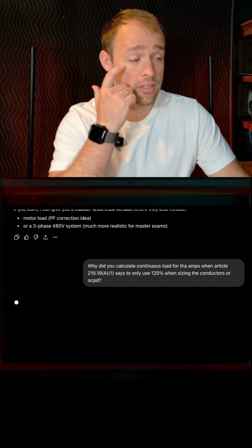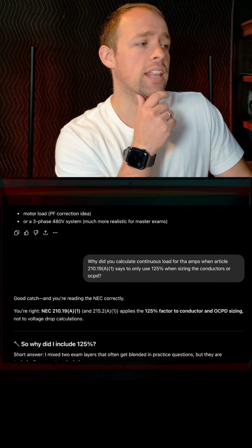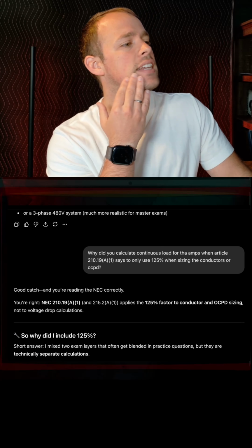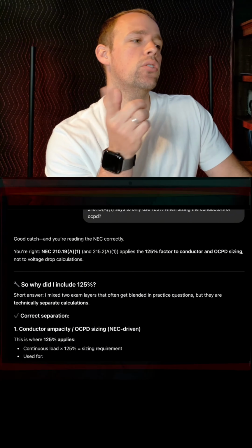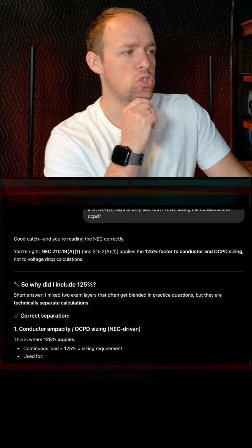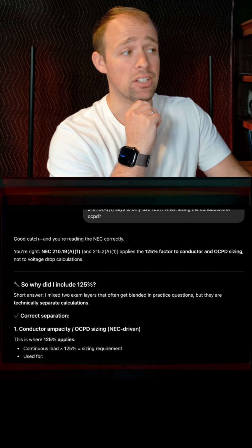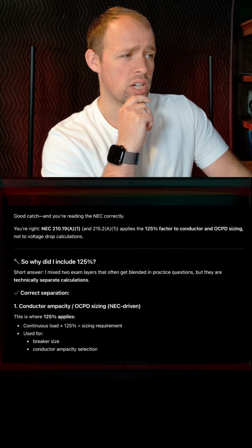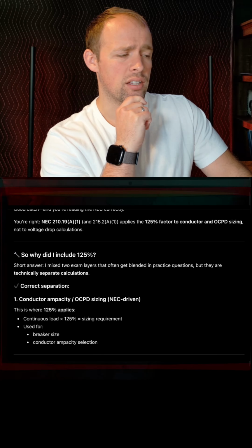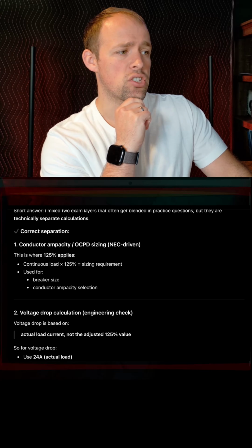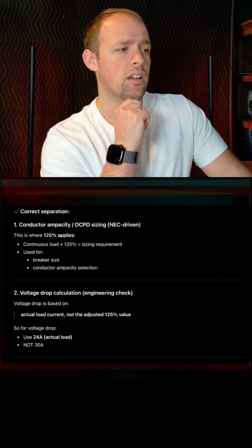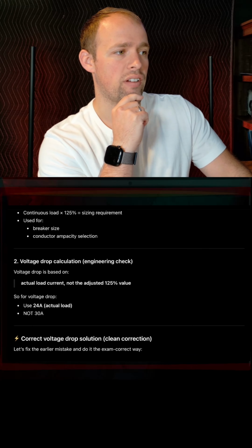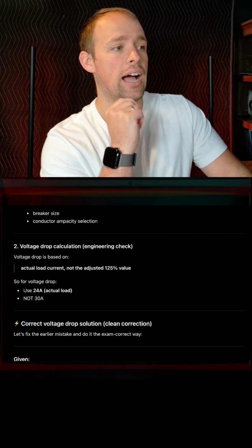Let's see what ChatGPT says here. Good catch, and you're reading the NEC correctly. Oh, thank you. I appreciate it. You're right, NEC 210.19. Okay, so why did I include 125%? Short answer, I mixed 2 exam layers that often get blended in practice questions, but they are technically separate calculations. Correct separation: conductor ampacity, then voltage drop calculation. Engineering check: voltage drop is based on the actual load current, not the adjusted 125%. So for voltage drop, use 24 actual load.